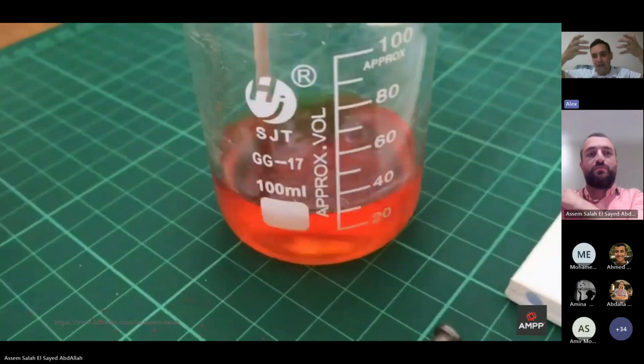I mean, when you get the vessel up, you see that go to maintenance. Yes, between the cycles of maintenance, these aluminum or zinc plates just decrease in size, get lower, and sacrifice themselves to protect the metal hull of the ship. But it works along with the coatings itself. It doesn't contribute much. I mean, it contributes, but just a small part for the protection, while the main part of the protection of the metal hull of a ship are coatings.